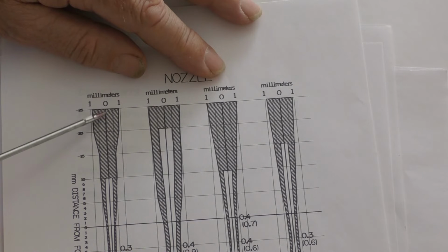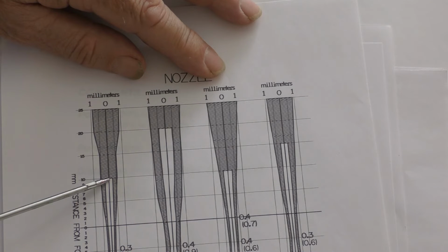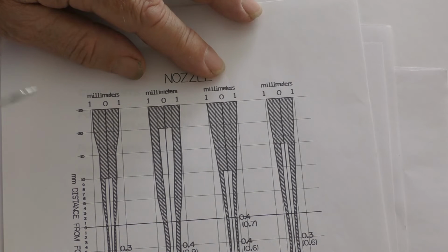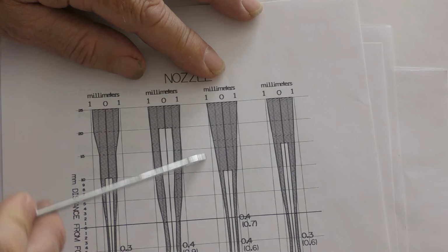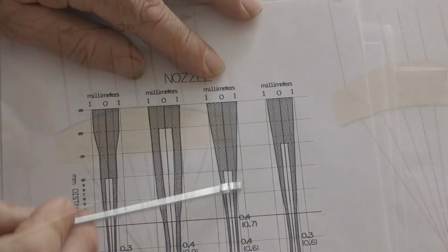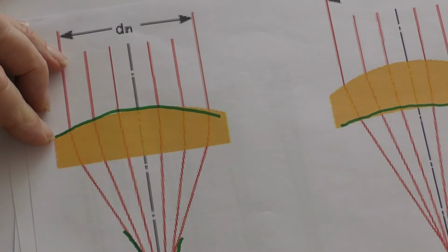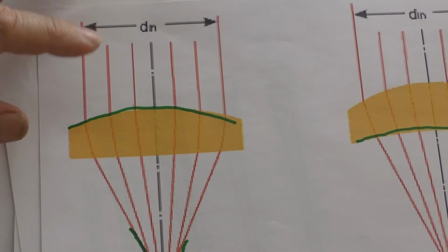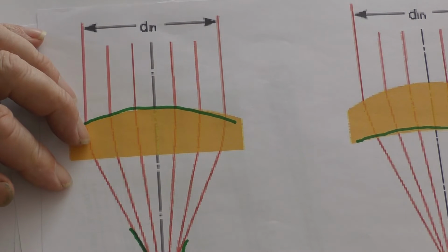These are energy density maps. There's two levels on here. We've got the hole, which is burnt through the card, which is this white section here, and the scorch mark, which is round the outside. What I can't do is tell you where the beam is, because I've got no way of measuring where the beam is, because it drops off to almost zero, but it's somewhere out here. Now, in principle, a spot size, regardless of what size it actually is, is the smallest point where the beams cross over, and you would expect the spot size to be constant.